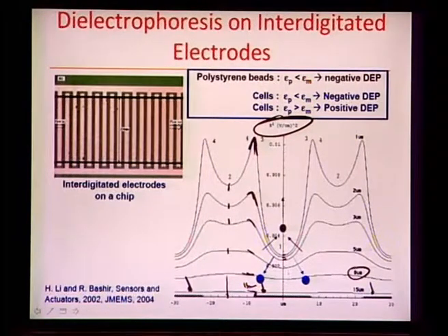There is no question of lines of force in this particular region, and the electric field is at an all time low in this particular region. So, if you have this kind of interdigitated electrode set as you are seeing here, with electrodes spaced from each other as a capacitor plate, you can have this kind of field distribution with a high field zone near the electrode edge, as you can see in both cases, and a low field zone in between the electrode edge, and then a further lower field zone in between the electrode itself, okay.